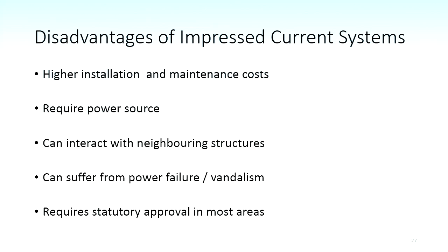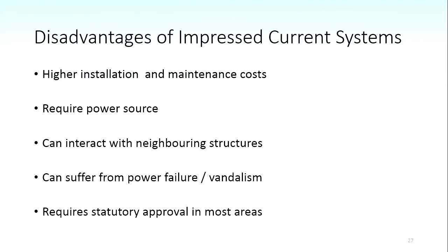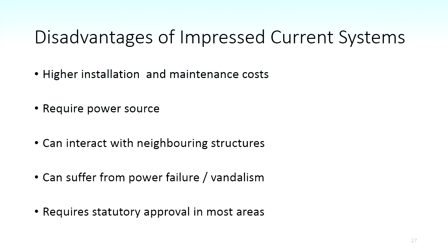Excuse me. What if there are any buildings or structures within the boundary where the current affects not only the pipe but any other structures like this? Anywhere where there's a significant electrical field being generated can start interfering with the potential on your pipe. And is there any method to protect those structures from the current? Can you shield it? They tend not to do that sort of thing.